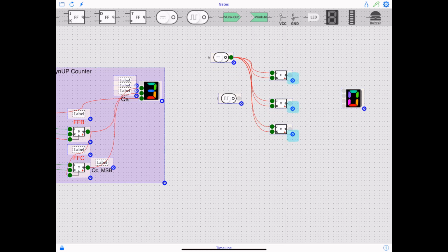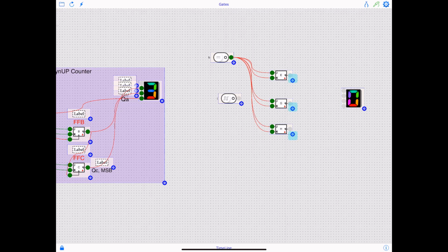Also, I'm going to click on this small gear at the bottom right of the JK flip-flop, and I'm going to make sure that I am choosing the clock. Because it was a negative edge trigger, I just need to tap on the negative. It's already negative edge, so I'm okay over there. Click OK, and as you tap on the clock, you see there's an extra input that comes here, and all I need to do is hook up my clock.